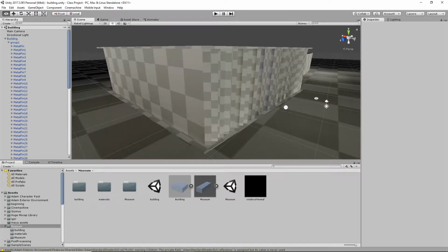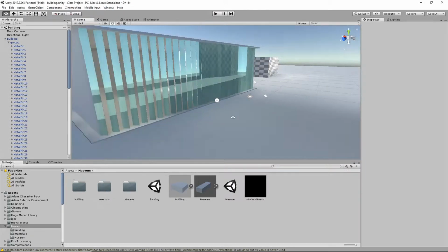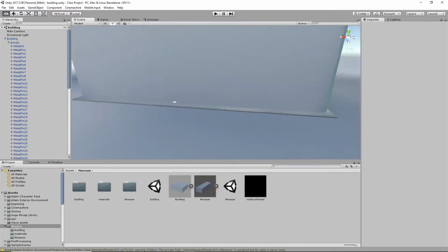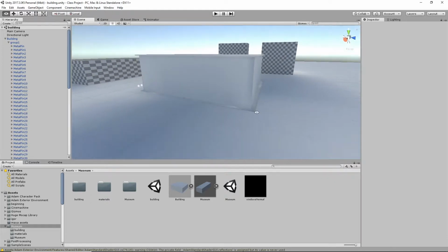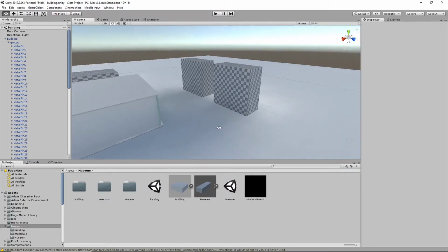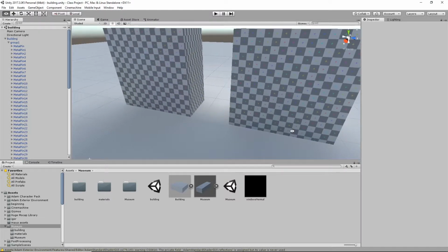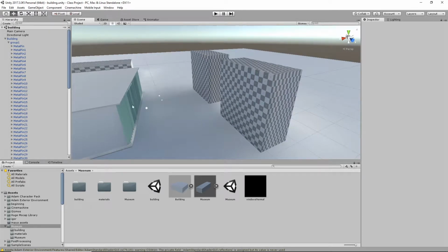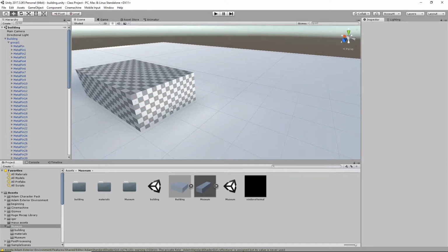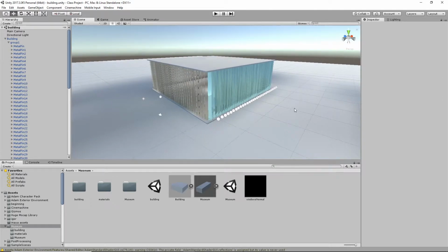So this is what the global illumination looks like in the baked light map editor. If we look at it in shaded, you can sort of see where light's bouncing, hitting walls. I'm getting backlit on parts. I'm using a low res light map, so it's taking a little longer. You can see where these walls are self-illuminating on each other. I'm not getting much bounce light here because of the distance, but you can probably see it the most right here off of this edge where it's bouncing and lighting up the plane. And you can sort of see it coming off of the glass walls here.